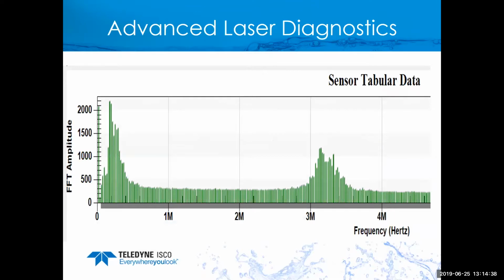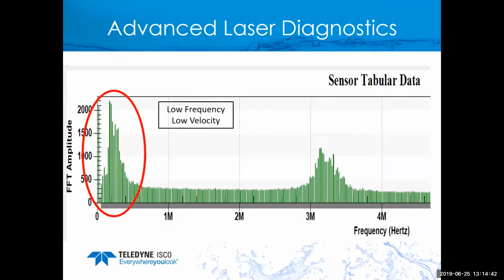When I looked at that, the velocity didn't look real hot to me, and there were a lot of dropouts in there. So what I did was I downloaded a diagnostic, again, the laser diagnostics. You'll notice there's a very low frequency, low velocity diagnostic or return spectrum. And then we also have a very high return spectrum. Well, that's telling me that we're getting the right reading, but we're locking in on the left. So with some of the advanced capabilities of the laser, we're able to actually avoid that low frequency thing and say, let's look to the right.